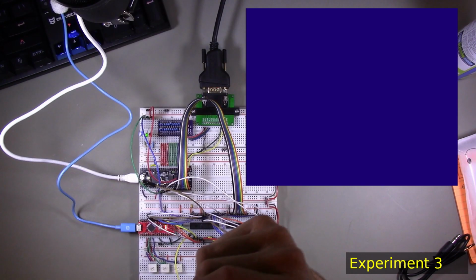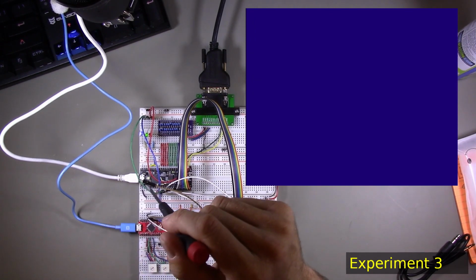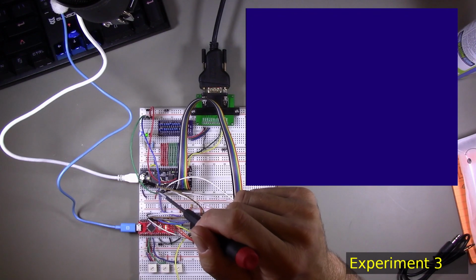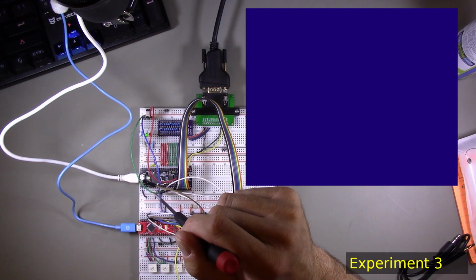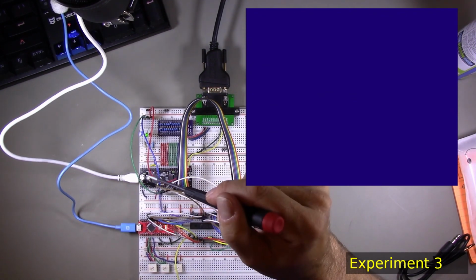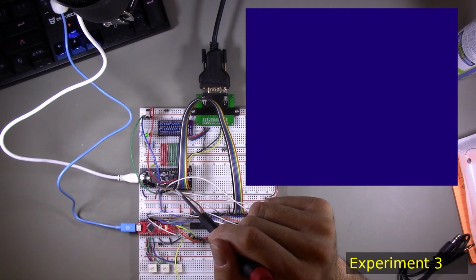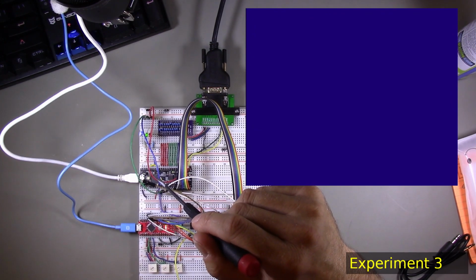This particular experiment took me a really long time to get working, and the problem was that I just could not get the data byte associated with the command byte to be processed properly, and it took me a long time to figure out what was going on. But what I eventually figured out is that the Verilog module that I wrote that basically acted as a 1-byte FIFO, so that the state machine that took data from the command FIFO could notify the command processing state machine when a byte of data had been received,